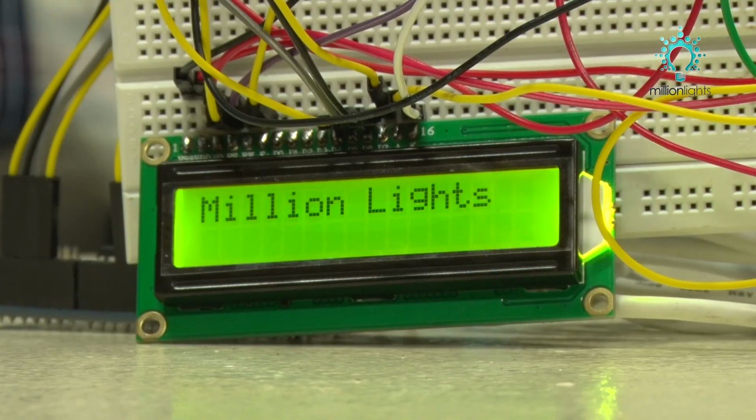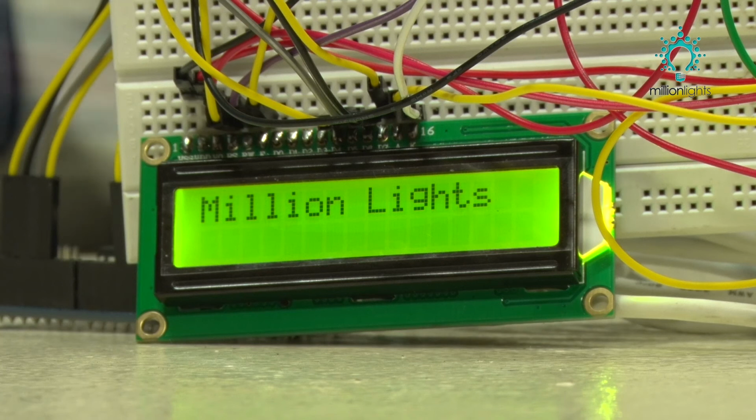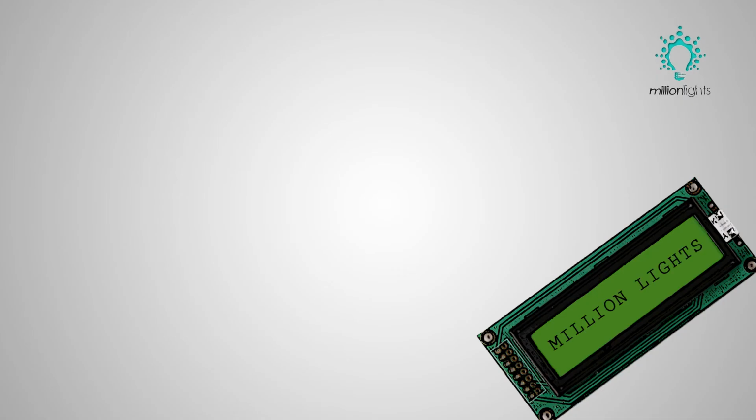Just take care that the data is of 16 characters or 16 digits including the blank spaces, because if it exceeds, then only 16 digits or alphabets or symbols will be printed and the rest will be skipped. For that we have to scroll it to the left and right. We can do that also, and we'll see that in the coming parts. So this is how you can display any text on the LCD with the help of the lcd.print instruction and setting the cursor.